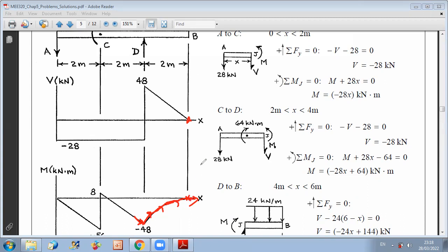So whenever you have at the end a distributed load, a concentrated force, or an external reaction such as a pin or roller, these will not lead to a bending moment at this point. To have a bending moment different from 0 at the extremity, you should have a couple acting on this point, or a fixity, because the fixity reaction can develop a reaction couple.